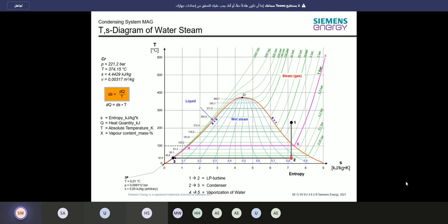But then condensation. So here I have steam, condensation happening all at the same 32.9 degrees Celsius. There will be no subcooling or something in the condenser. And then it's getting to here where I have 100% water, or condensate again, with 32.9 degrees Celsius. And from there, I'm getting back into the condensate pumps, increasing the pressure, bringing it to the system again, and that's what's happening. So I don't have any subcooling or something inside the evaporator. This is not happening.